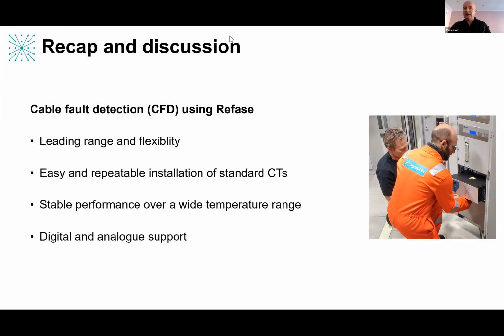There's another question there that I could maybe answer. It's basically saying that when the overhead line is connected to cable, there's a change of impedance at that point, which will reflect signals from that discontinuity in impedance if this is traveling waves that we're talking about here. The question is how is this handled in terms of reducing the measurement sensitivity? So I would go back to what we were saying earlier. For this faulted section identification, we're relying on measurements of the fundamental frequency components and looking at a simple differential comparison. So this wouldn't really impact at all on this kind of multi-zone differential.